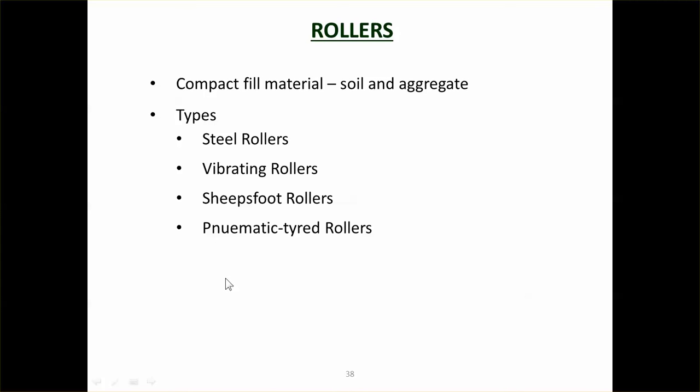So rollers are used to compact the soil. One of your first challenges is to get the soil to the optimum moisture content, or plus or minus 2-3% of the optimum moisture content, and then you put rollers over top of it. What the rollers are doing is applying force, either static force or vibration, to the soil particles to get them into a denser state. And there are different types of rollers according to what the soil is and what you're doing with it.